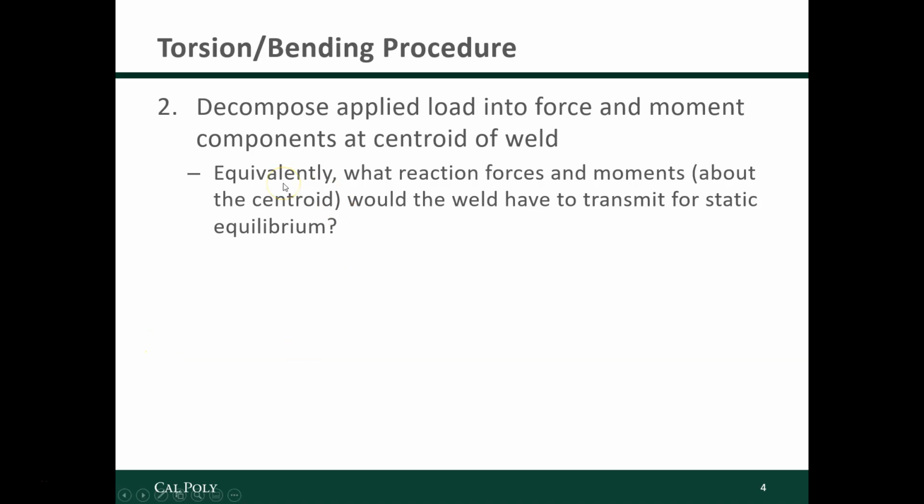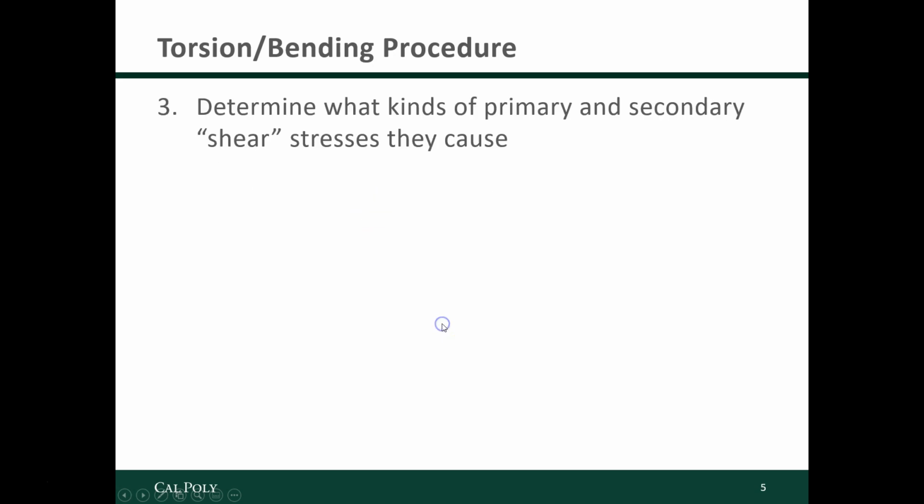Missed that, but as a review, equivalently, what reaction forces and moments about that centroid would the weld have to transmit for there to be static equilibrium? 3. Determine what kinds of primary and shear stresses that they cause.